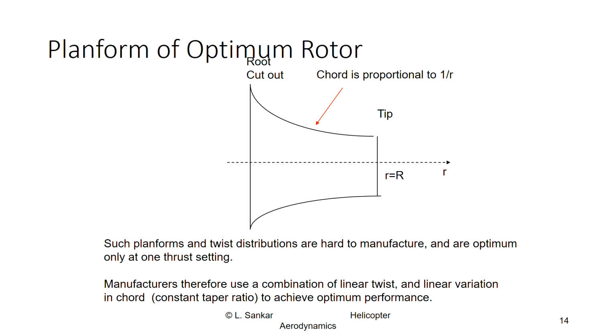So very often people will go with rectangular blades, or sometimes they will taper right near the tip region, because the tip produces a lot of thrust, but the tip also consumes a lot of power. If you look at some of the Blackhawk rotors, the UH-60A had a rectangular planform and rectangular swept tip. The UH-60L or M, I've forgotten which, had a tapered rotor right near the tip.